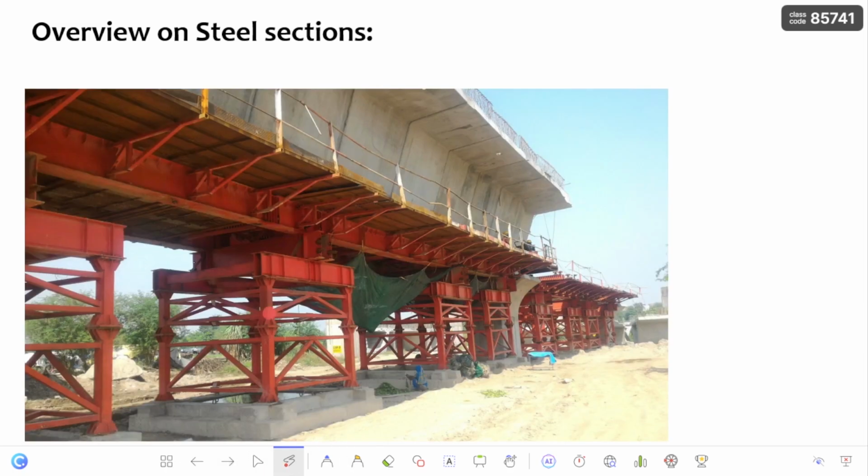Next, coming to the other applications, these are the trestles which are used to support the permanent structures, and later after casting of these permanent structures, these trestles are going to be removed. These trestles are going to resist the compression which is coming onto the structure. I already discussed why we use these hollow sections in case of compression, because it is symmetrical in both directions.